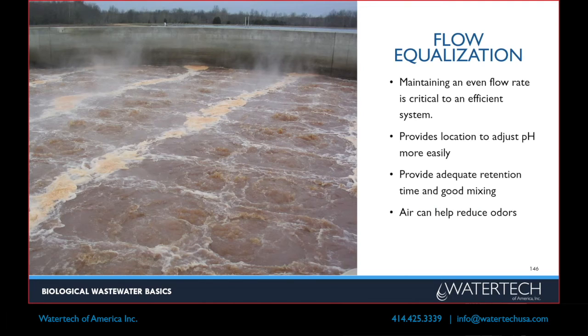Flow equalization: it's a big flow equalization tank, in lots of places, especially food plants. With CIP in the evenings, you get 80% of your flow and loading then. If you have a nice equalization tank, it can buffer that and run it through your plant the rest of the day. It equalizes the organic loading because most of it is coming at night, so you dilute it down with the flow from the rest of the day.